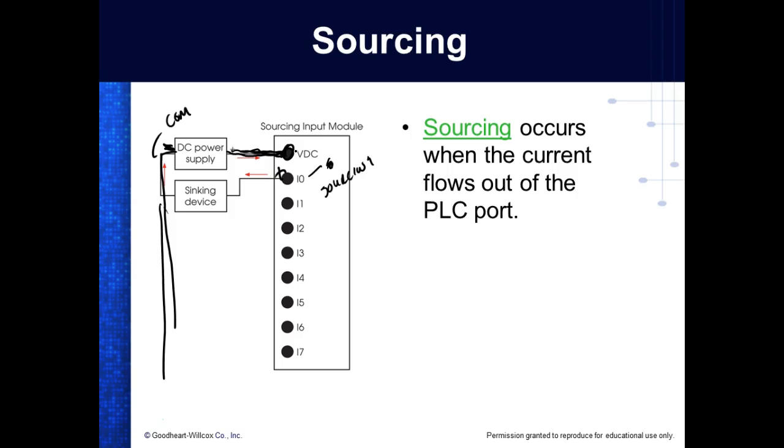Because I have to supply the what? If the module supplies the negative, then I've got to run the plus to everything. If my module supplies the positive, then I've got to supply the negative. So this is a syncing input.